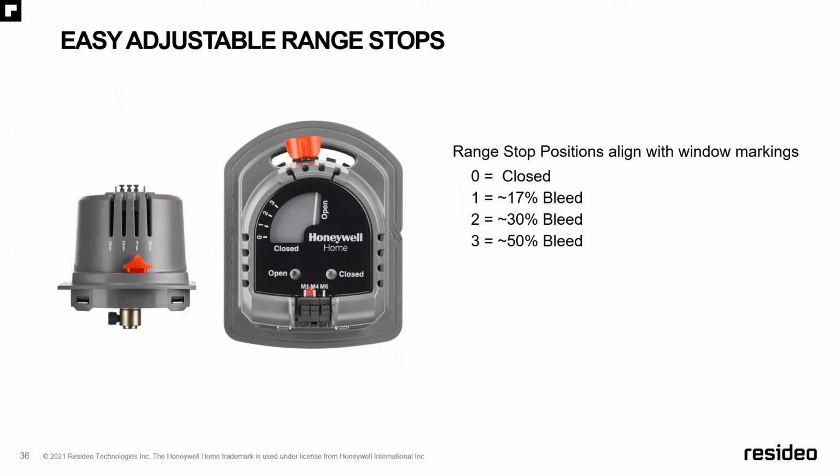Now, even though you have 3 low voltage connections here, you typically are only going to use the M1 and the M6 connection, because what this is going to do is drive the damper closed, and it's going to light a red light here when it's completely in the closed position, or one of the pre-selected positions when it's done with its movement.